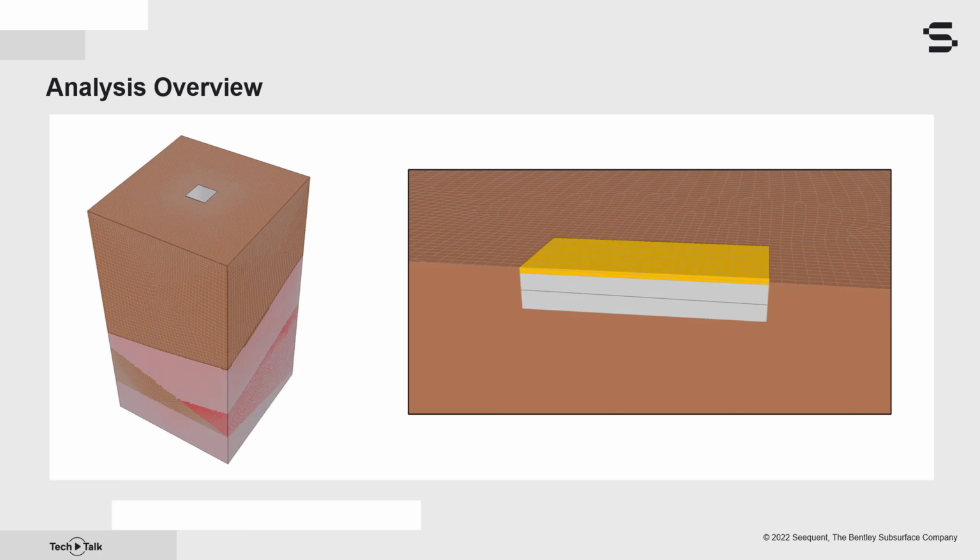Here is a cross-section of the building foundation. The building lies on 0.25 meters of extruded polystyrene foam insulation, overlying 1.5 meters of non-frost susceptible gravel. 3 thermosyphons are installed in the gravel portion of the foundation, with a spacing of 3.33 meters on center. The position of one of these is visible in this cross-section. The thermosyphons are sloped 3 degrees from a horizontal reference.